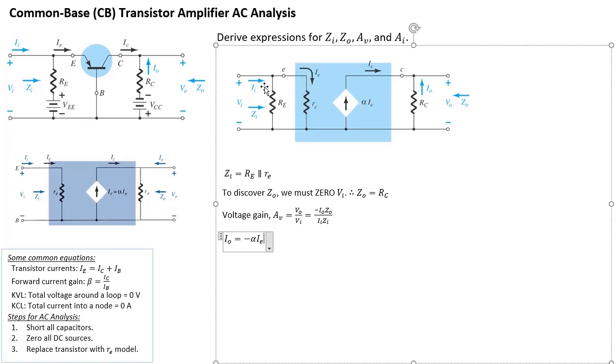So that's what II is going to do. It's going to split between these two resistors. So we can write an expression for IE relating IE, RE, small re, big RE, and II in terms of a current divider rule. All right. So I can write here using current divider rule.